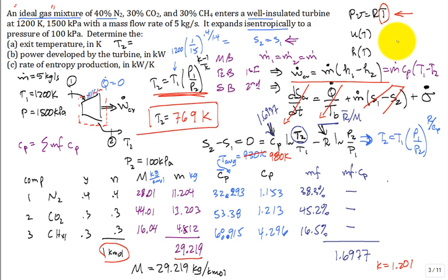I will ask a clicker question. A, yes I can. B, no I cannot. Let's start this clicker question. Somebody says, I think you can calculate it by replacing delta H by C sub P delta T. So instead of M dot H1 minus H2, it's M dot C sub P T1 minus T2.